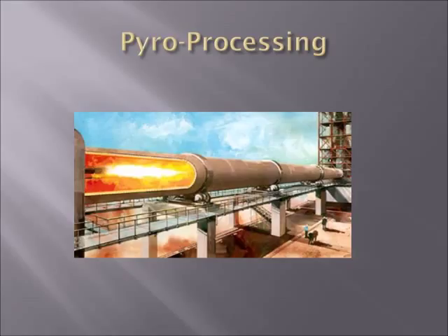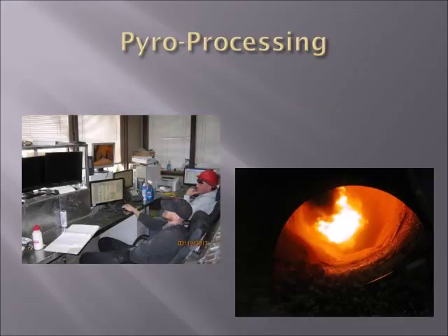First, there's the removal of moisture, then you get into the calcining phase, then as it reaches the burn zone, the material becomes red hot and plastic, where the gases that are created internally trying to escape cause the material to expand or bloat. The operation of the kiln is computer controlled and continuously monitored 24 hours a day, 7 days a week, 365 days a year.